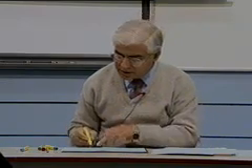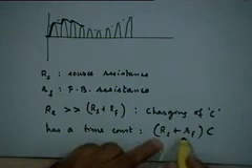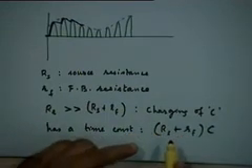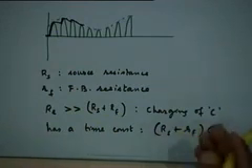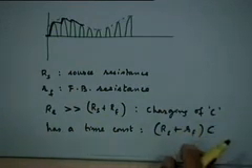If you were to calculate the charging time constant more accurately, what will it be? The resistance involved will be RS plus RF in parallel with RL. So all we are saying is RL is much larger than this, so therefore the parallel combination behaves more or less like RS plus RF itself, right? So that's another way of looking at it.